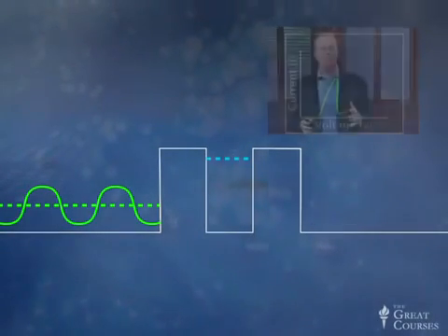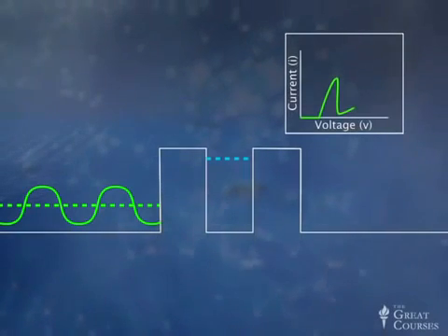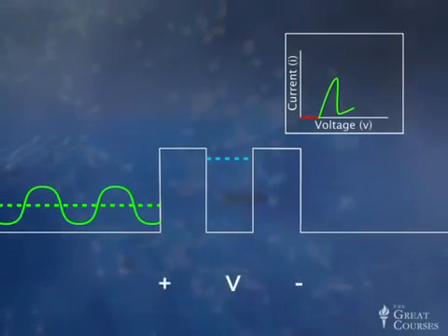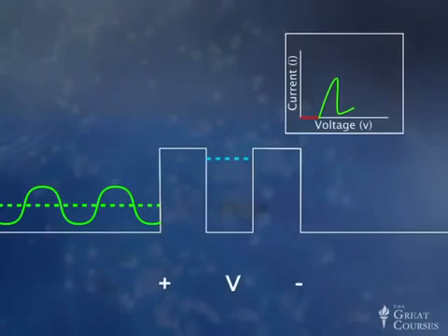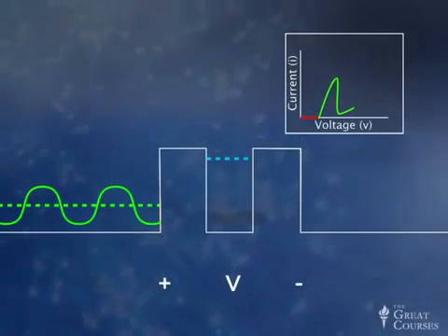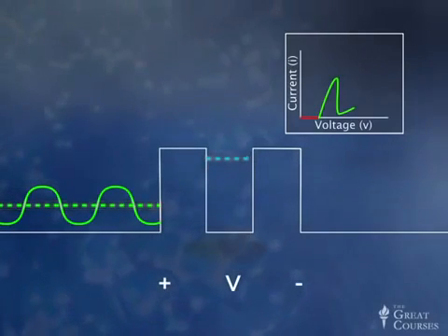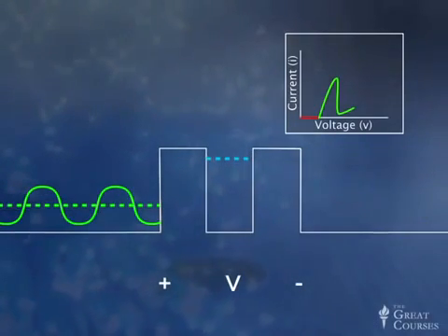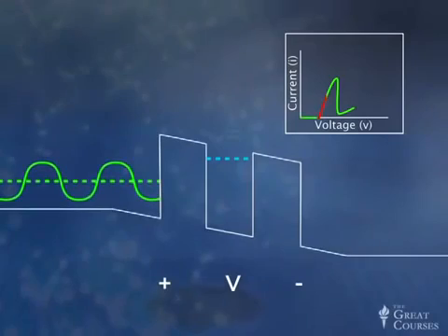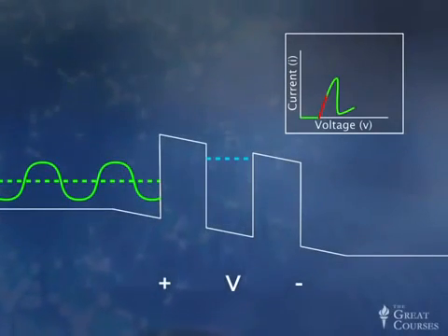And so what we do in a resonant tunneling diode is we apply a voltage. Applying a voltage is just giving an electron a bit of energy, so we can raise it up in energy. But until it sees this resonant transmission, this tunneling phenomenon, it's not going to go over to the right with any reasonable probability. And so we raise our voltage a bit, and essentially no current flows.